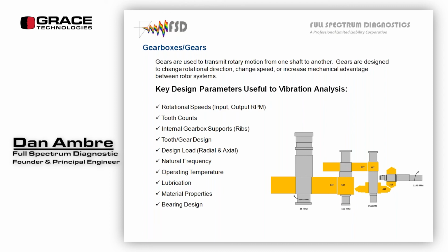And then at that same location, we're going to look at a higher frequency range so that we can see the gear meshing frequencies. And we'll talk about this later, but we're looking up to 3 gear meshes. So not 3 different gear meshes, but 3 times gear mesh frequency on each meshing condition. So these 2 gears are touching, they share a gear mesh.